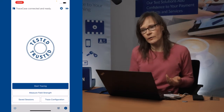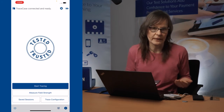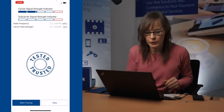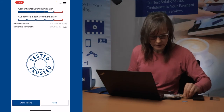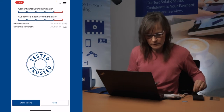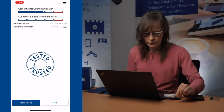And it's also very helpful in the laboratory if you want to find out if a card is answering at all, or if a reader is emitting any field at all, if it's active. Therefore we have built in the feature measure field strength. So I take my antenna, the small one, and you can see that the reader is active, and you can also see if you go far away, the signal is vanishing. If I come near, the signal strength is increasing, and if I go too far away, it's going to 0 again.